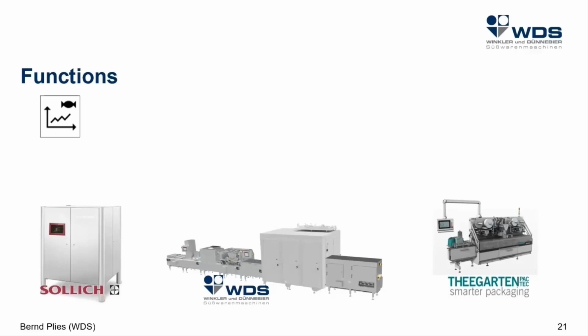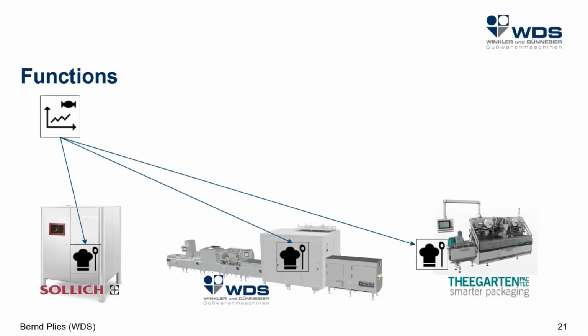So the higher-level system provides all necessary order data for the intended next production sequence via the standardized vertical integration by Weihenstephan standards. This order data, together with the product type behind it, then automatically determines via the interface the required recipes and parameters of the machines involved in the product manufacturing. Every single machine can activate the right recipe at the right time via the mechanism of the sliding or floating order change.